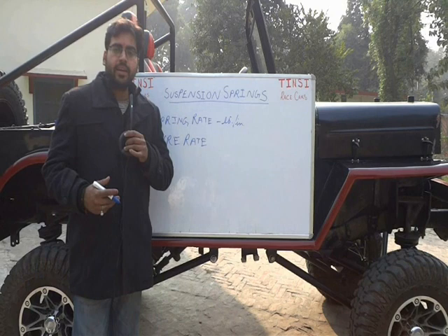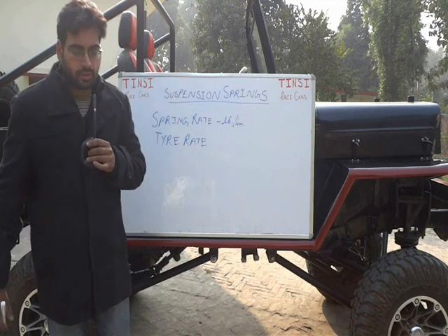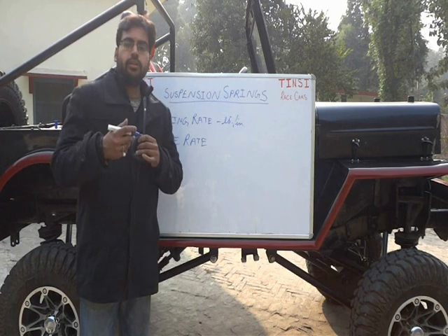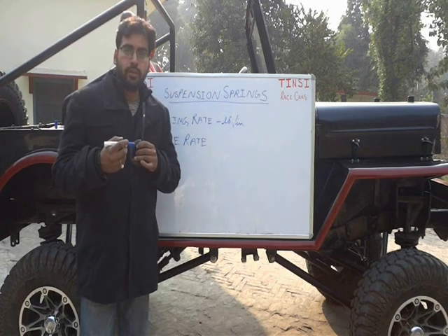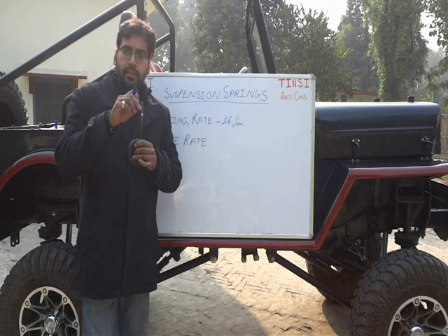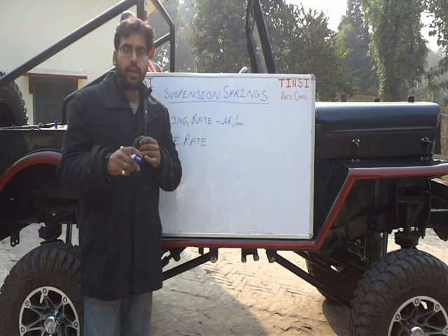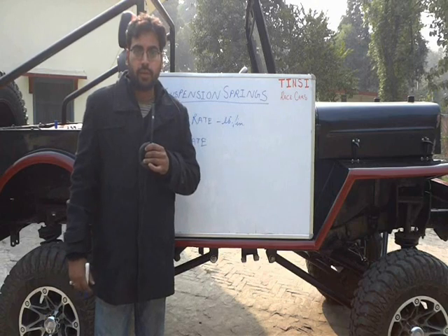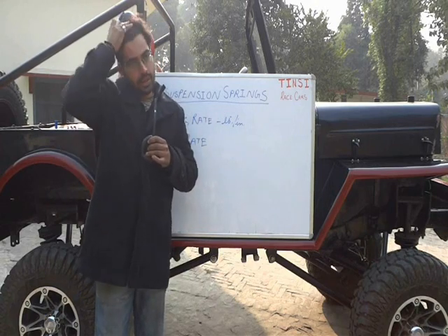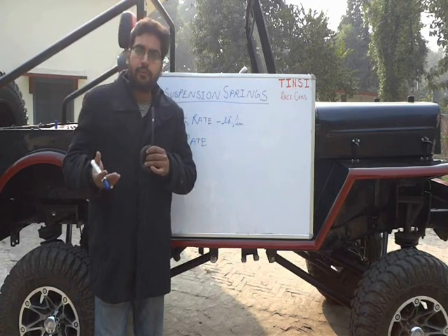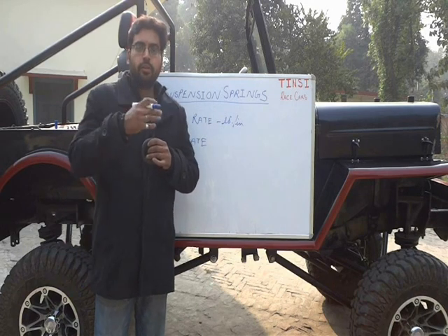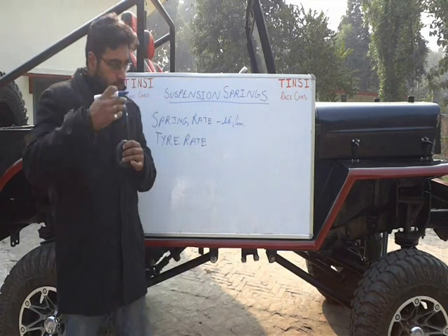So after the tyre rate, we go into the ride rates. Ride rate is the vertical force per unit vertical displacement of the tire at the center of the tire spindle, which is measured relative to the chassis. Okay, so this is actually the travel that you are experiencing, and the force that is causing that travel is called the ride rate.